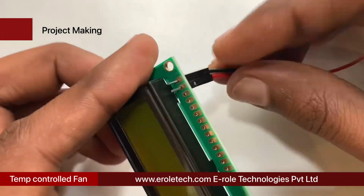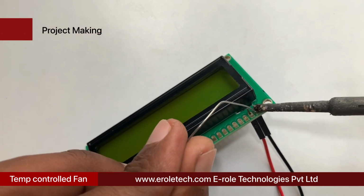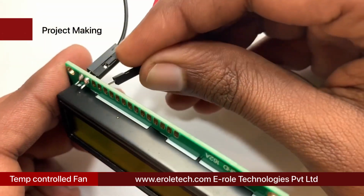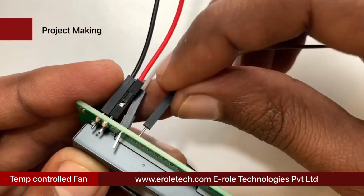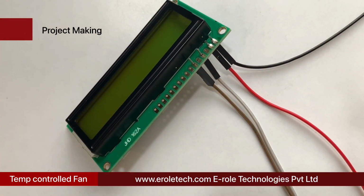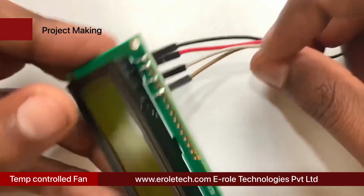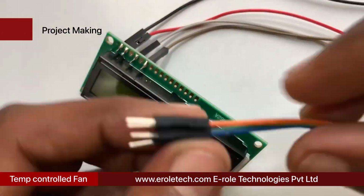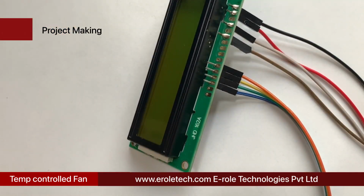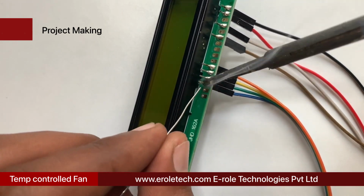Now we will solder a black wire at hole number 1 and a red wire at hole number 2 of the LCD display. Now we will solder a white wire at hole number 4 and a brown wire at hole number 6 of the LCD display. Now we will solder orange, yellow, green, and blue wires at pin numbers 11, 12, 13, and 14 of the LCD display.